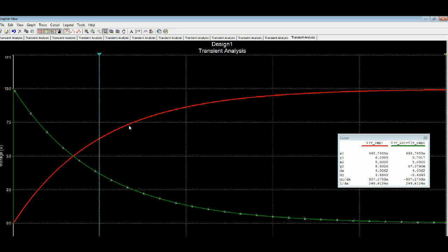And then in the second time constant, if we wanted to look at that, and this is a little bit tricky, the voltage between the first time constant and the final voltage would be 63%. So the voltage between here is 63%, where from here to here is 100%. So every time constant we go out, we converge on 10 volts by 63% of what is left. And the same is true with the current. It's converging on 0 based upon 63% also.